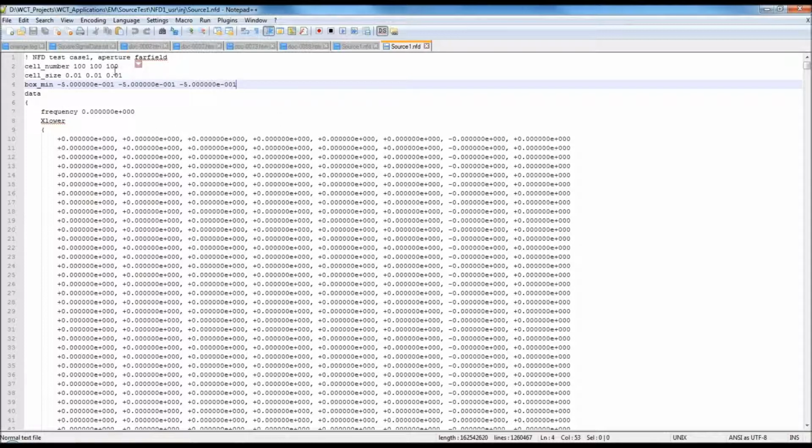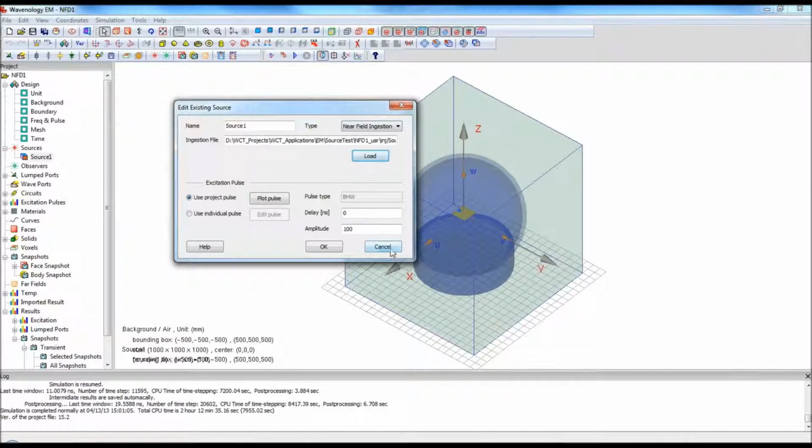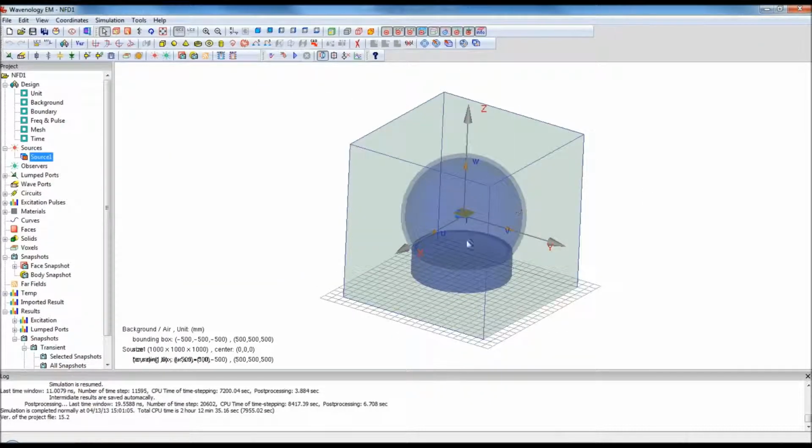You can see this is very huge data at certain points. So it doesn't have to match the FDTD grid inside the software. The software can resample the data and convert it into time domain pulses as well. Okay. So for example, in this case, you give several frequency points. You give the field at all the locations from your measurement using this format, NFD format, and then the software can recognize that, load it in, and you will see this is a radome together with some receiving antennas inside.